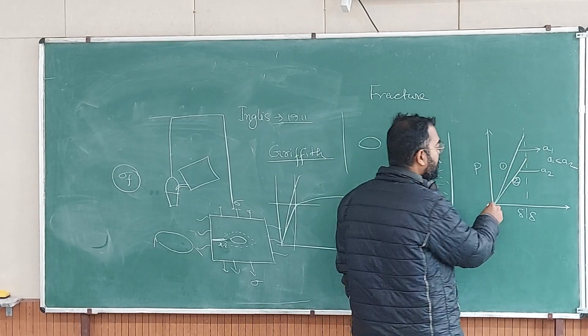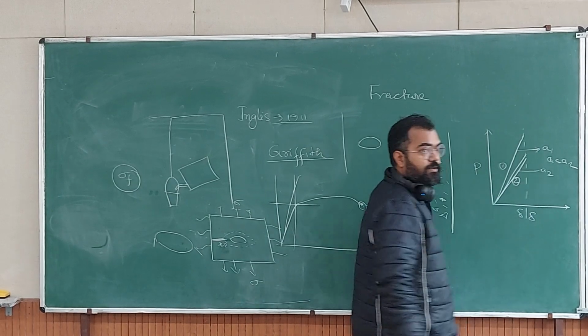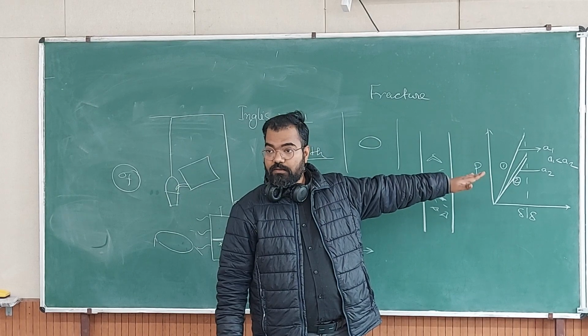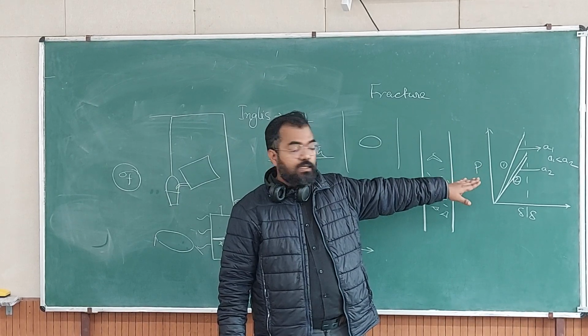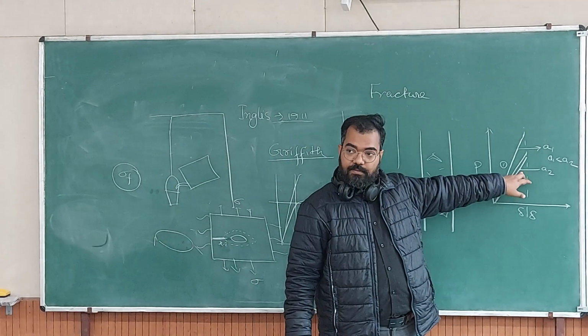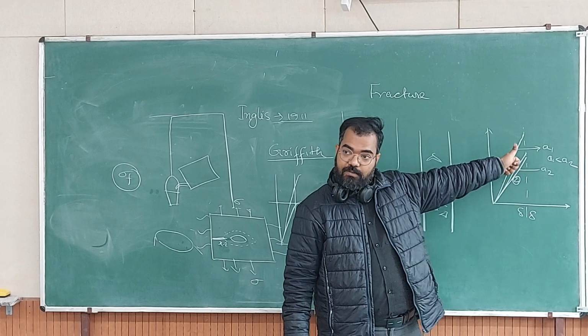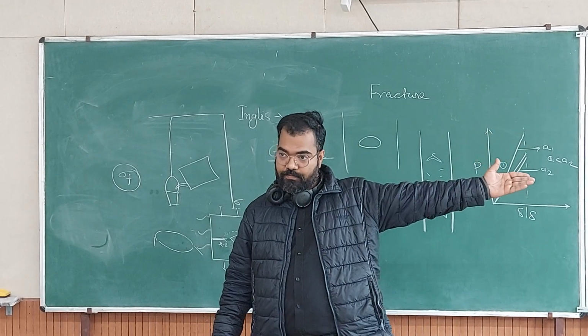So in this case, with plasticity, you can say that the force will be a little higher in comparison to what? In comparison to the final crack length. Whatever energy is needed for the final crack to extend to the same displacement, a little more will be needed because that is going into plastic consumption, right?